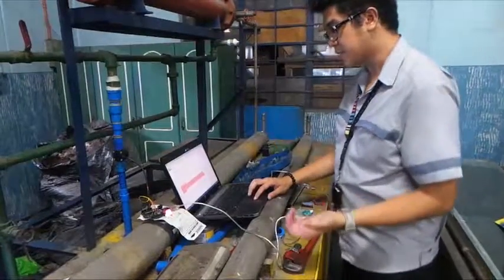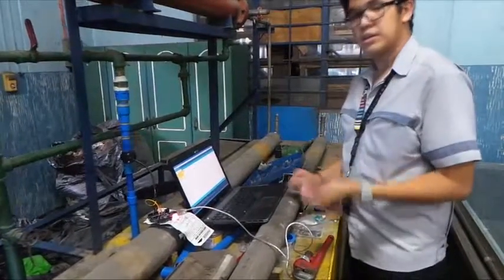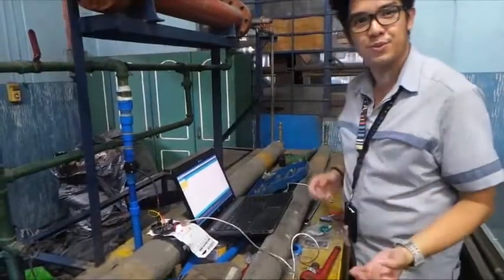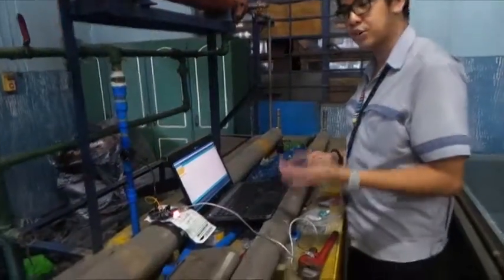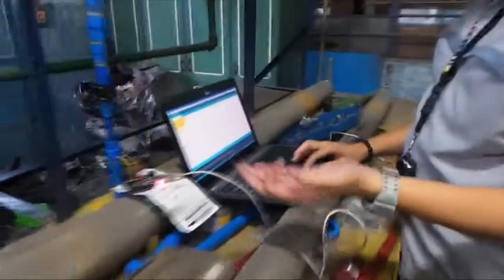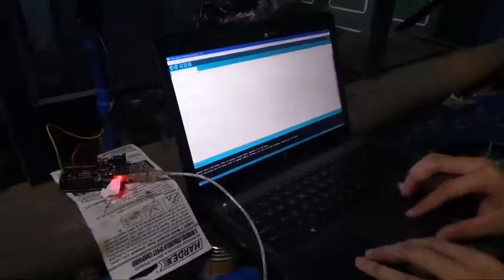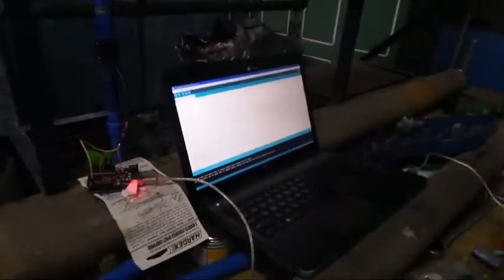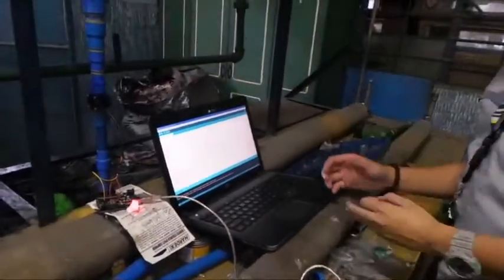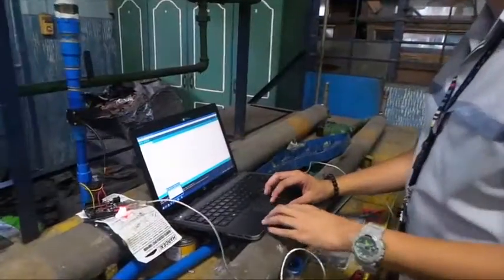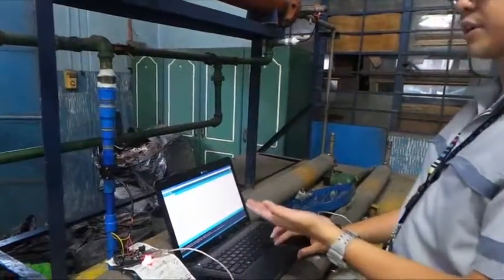Based on our experiment in the last video, the pulse flow calibration factor is exactly 4.48, which we use in our program so that our liters per hour can be accurate. So here we're going to test our flow sensor by showing you in this program.